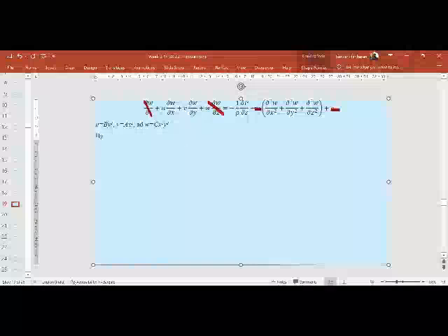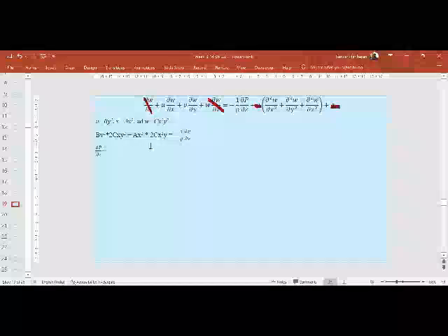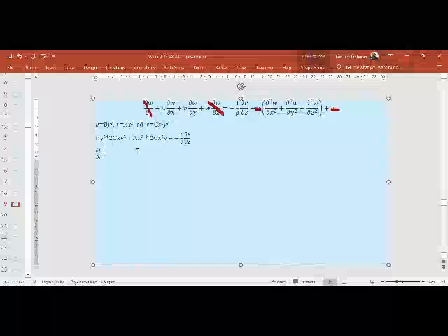We know that U is ay square, and we have to multiply that with dou W by dou X, which is 2cxy square, and V is ax square, and you have to multiply that with 2cx square times y. And that we have to equate it to minus 1 by rho dou p by dou z. Therefore, dou p by dou z, we can write it, from here we can simplify it by taking out c into x square y.